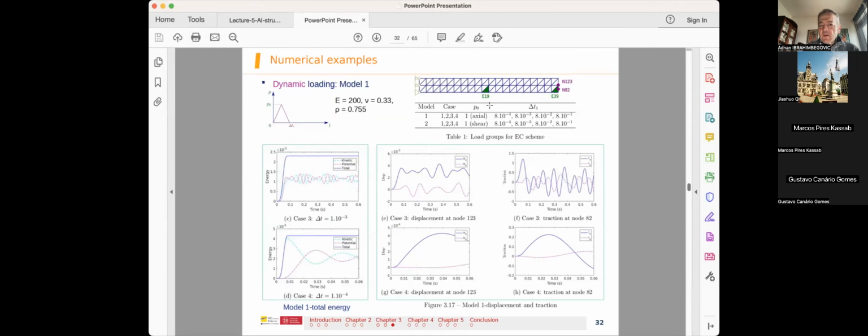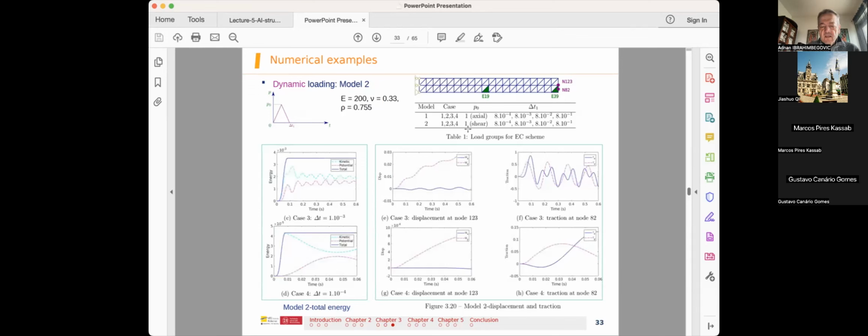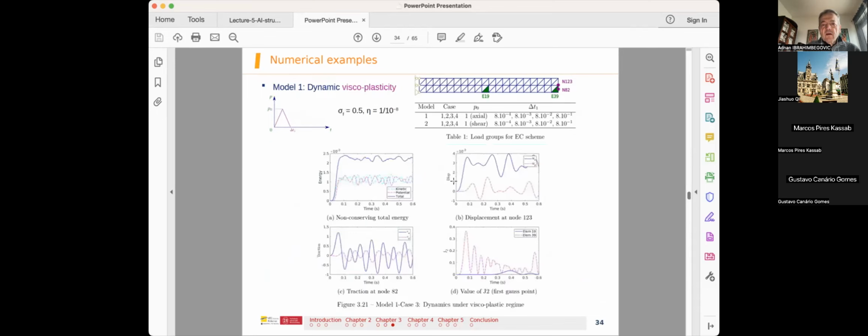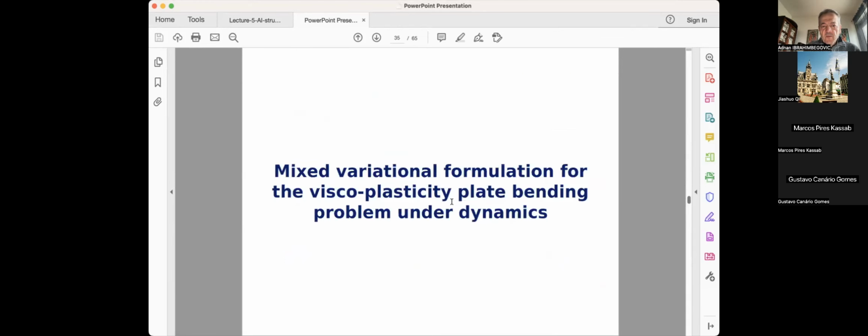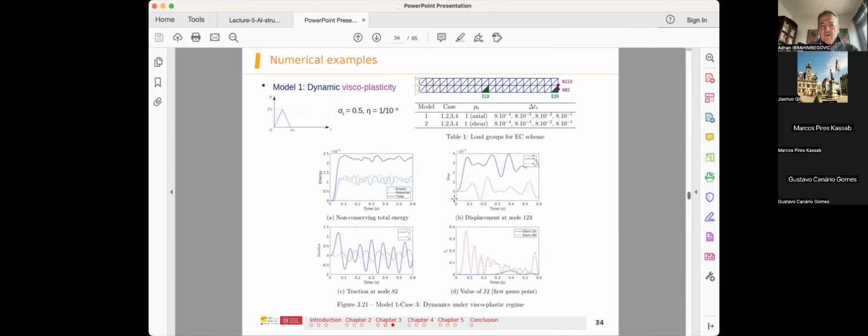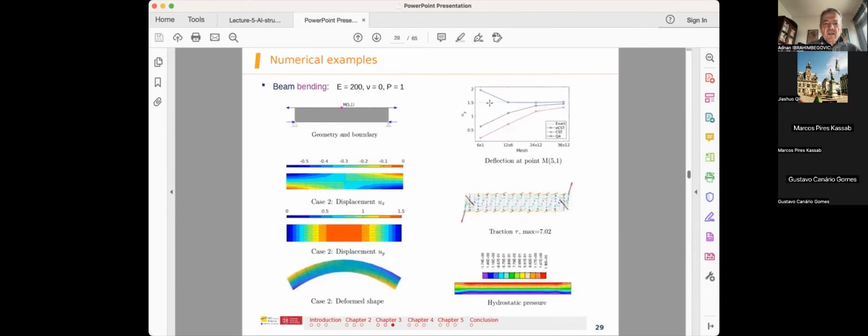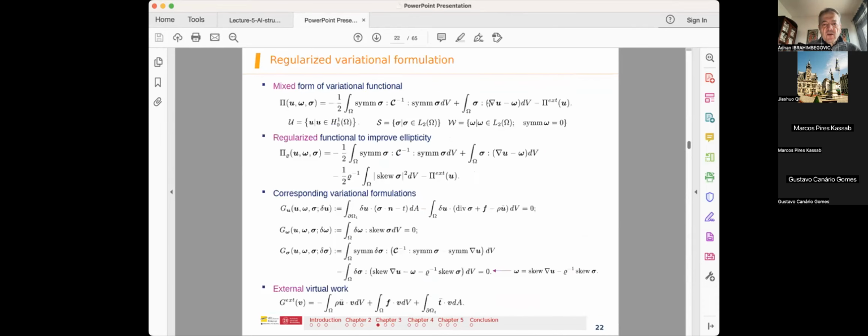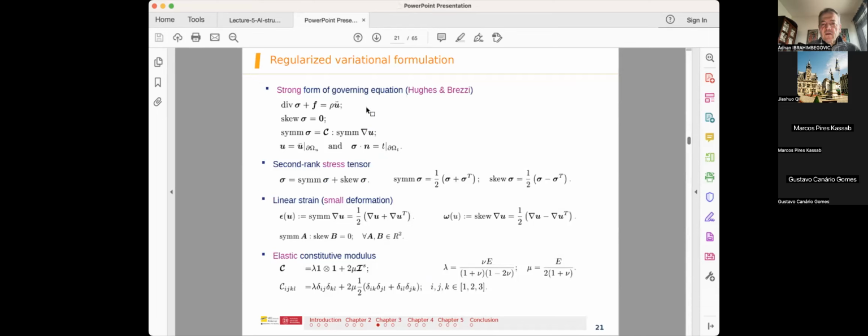And then you can also play with different types of triggering, viscoplasticity and here and there, and still handle this. And then you have something with, let's say, long-term loading with the conserving energy. If you remove, let's say, the plastic dissipation, there's no problem. So we were able to show that the computation can go into very long term, and then you can even do an energy decaying scheme to handle, say, some kind of presence of high frequency vibration that could be typical of this problem.